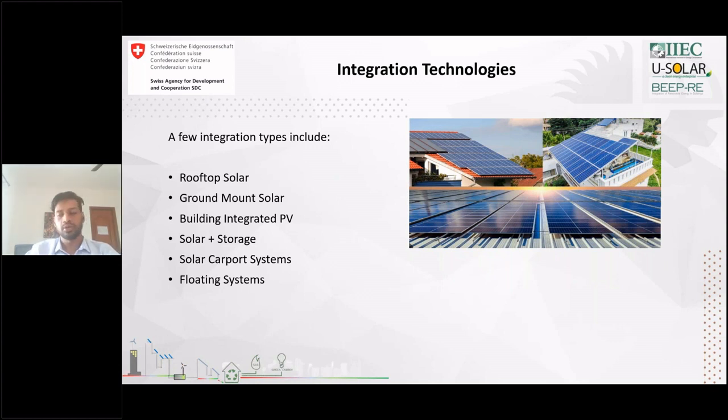With rooftop solar, there are huge space constraints, as most factories or industrial or commercial spaces have very limited roof space. In industries, if they opt for a shed roof, the scalability will be pretty good. But when it comes to an RCC structure, or in urban areas, we have a lot of restrictions on rooftop space.